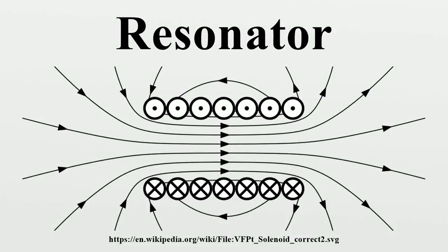A resonator is a device or system that exhibits resonance or resonant behavior, that is, it naturally oscillates at some frequencies, called its resonant frequencies, with greater amplitude than at others. The oscillations in a resonator can be either electromagnetic or mechanical. Resonators are used to either generate waves of specific frequencies or to select specific frequencies from a signal.